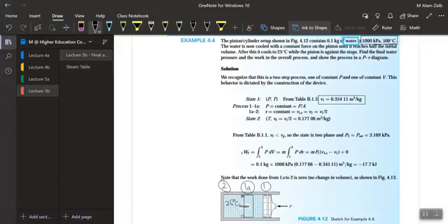It might be having a different steam table, and that is cubic meter per kg. Now, when we are cooling from V1, when we reach the stop, which is somewhere here, the volume is half, like volume would be divided by 2. So V2 would be equal to V1 divided by 2, which is equal to 0.17706 cubic meter.